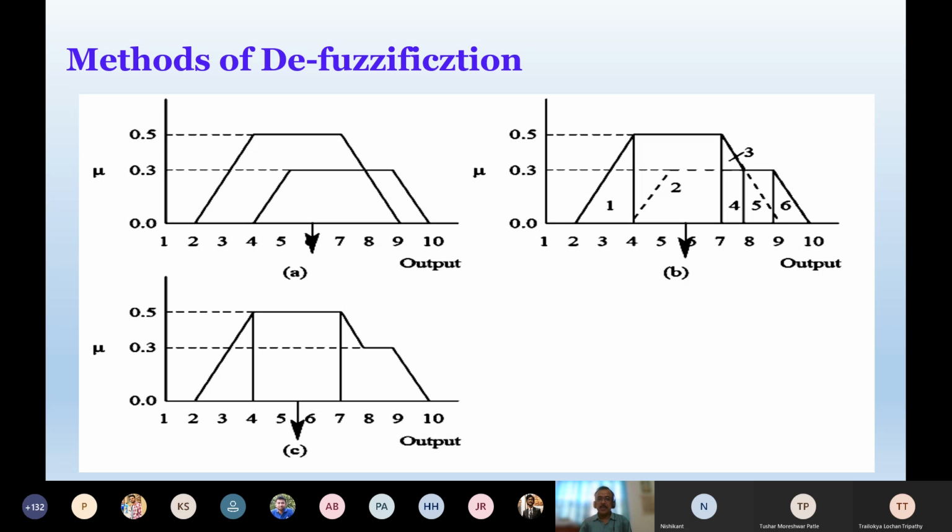Take it from me. The point I'm going to make is that the method of defuzzification is not the prime factor. Take any one. You train your fuzzy logic controller with the help of one optimizer, say a genetic algorithm, with some training data, and after that, my fuzzy logic controller will be able to perform in the optimal sense.